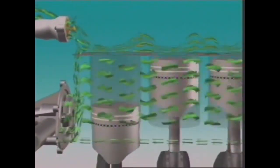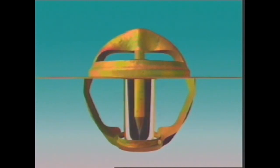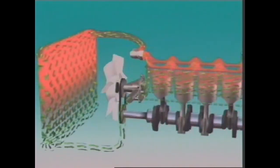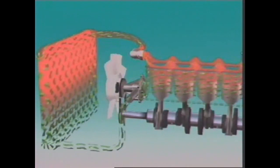When a cold engine starts, coolant circulates within the engine block and cylinder head and through a coolant bypass to the water pump inlet. It can't get to the radiator. As the engine warms up, the coolant in the engine gets hotter and hotter. This thermostat has a wax-like substance that expands as the engine nears its operating temperature. This starts to open the valve. Coolant starts to flow to the radiator.